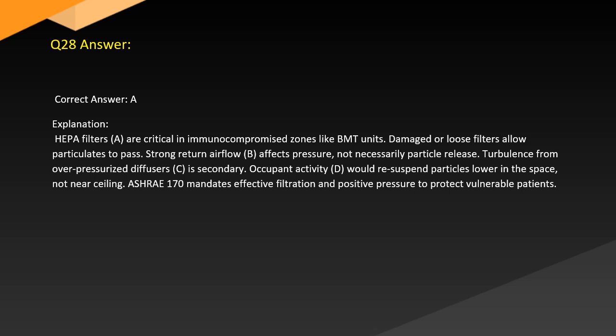Turbulence from overpressurized diffusers (C) is secondary. Occupant activity (D) would resuspend particles lower in the space, not near the ceiling. ASHRAE 170 mandates effective filtration and positive pressure to protect vulnerable patients.